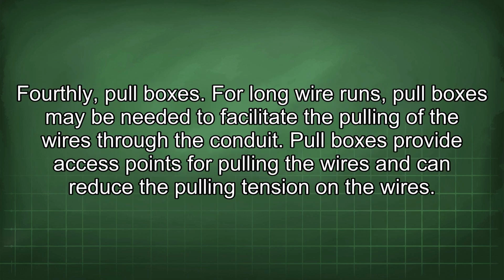Fourthly, pull boxes. For long wire runs, pull boxes may be needed to facilitate the pulling of the wires through the conduit. Pull boxes provide access points for pulling the wires and can reduce the pulling tension on the wires.